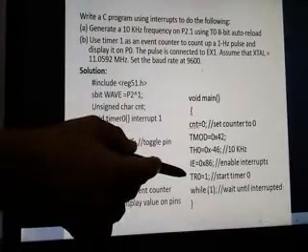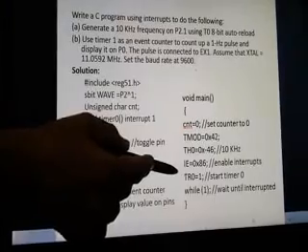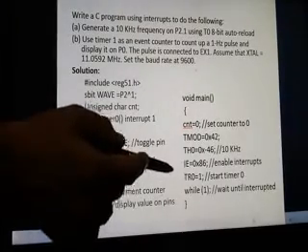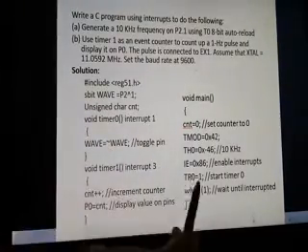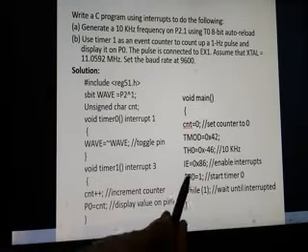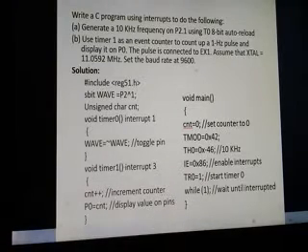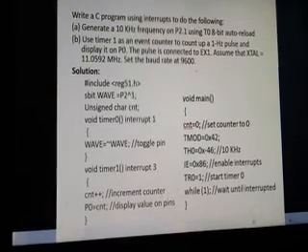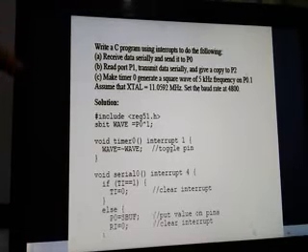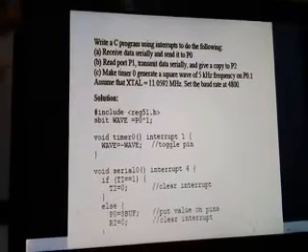Configure IE so that timer 0 and timer 1 both are enabled and EA is also enabled. So this becomes 86. Start the timer and give a while 1. This is one more classic example. Many more are there in the book. You can go through the remaining ones. We'll quickly do this last one.